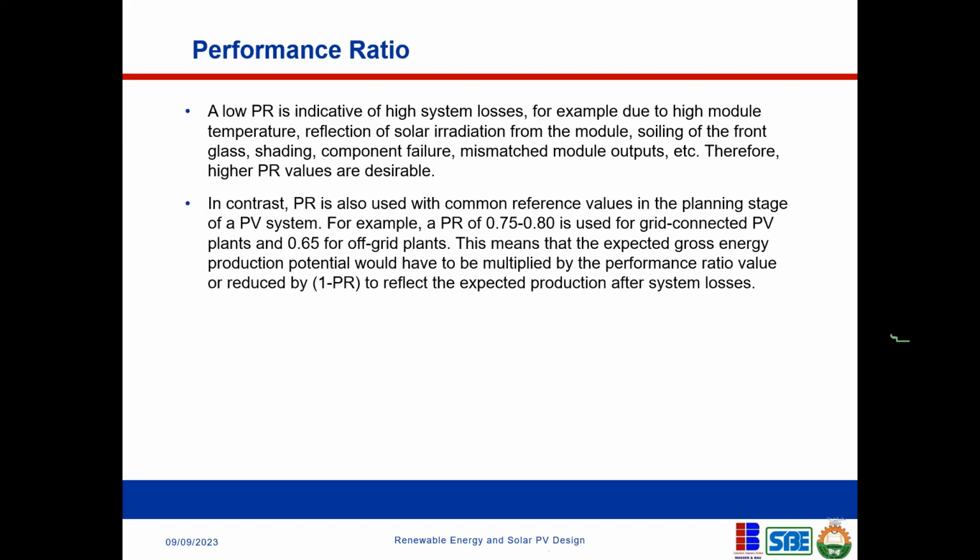In contrast, performance ratio is also used as a common reference value at the planning stage of a PV system. For example, I think I've already said it, when you're doing your PV design, perhaps you might not be able to know what the performance ratio should be, just like Engineer Uche just rightly explained. You might use it as a safety factor, so you don't overestimate, especially when you're doing an investment grade assessment.